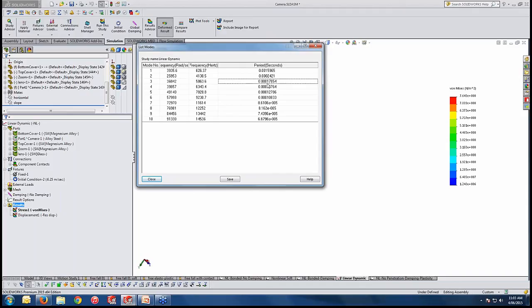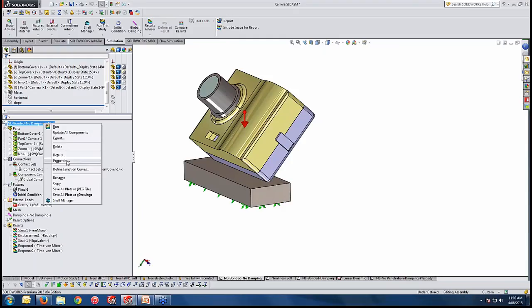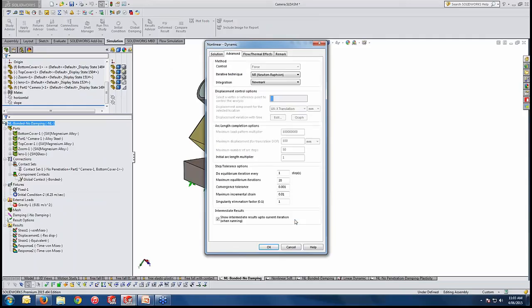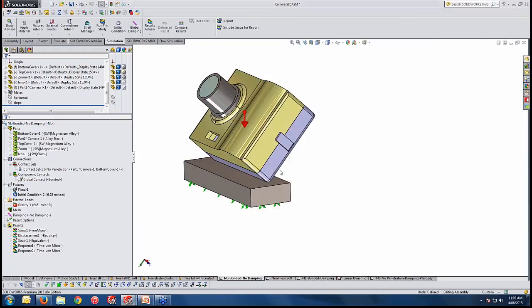So it is 1e-4, and what we have set up with no damping here, you can see I have put a very tiny time step to create the stress on the model, and just recording 5e-5 on my system. All right, the rest is about your advanced options, which is using the force control and the other factors for eliminating singularities, your convergence tolerance, and maximum iteration if you would like to set it. From this point, the nonlinear study is ready to perform.